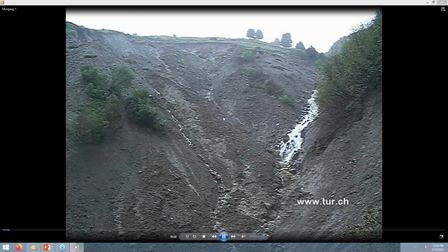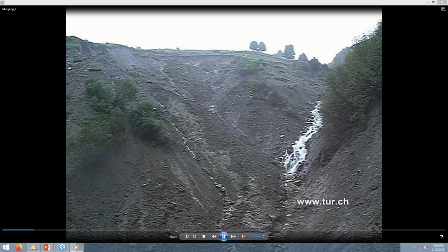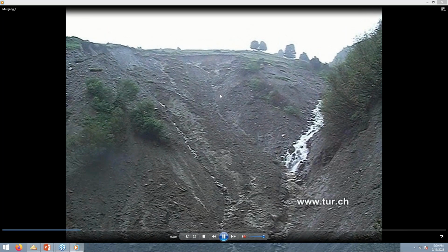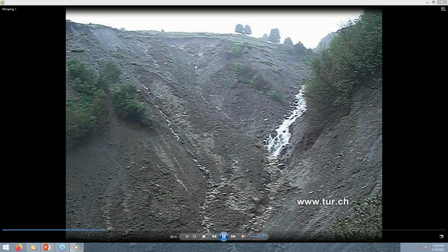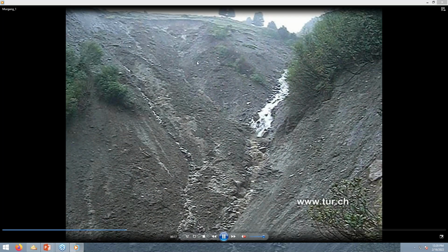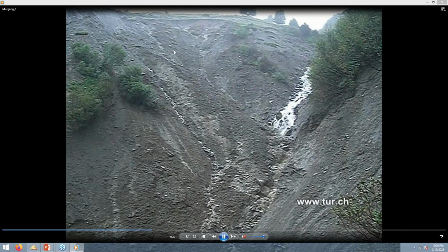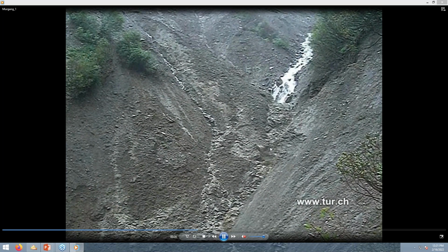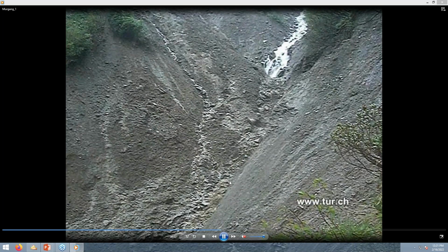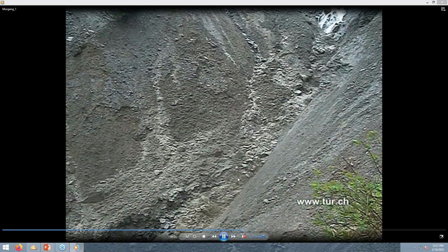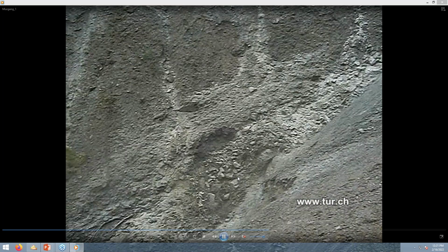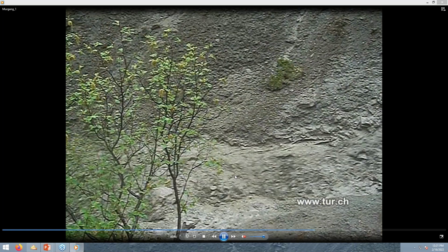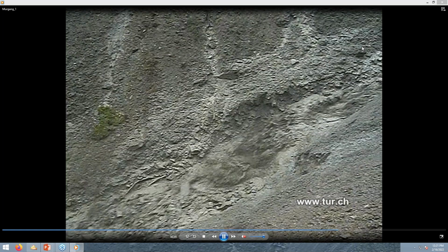Let's watch that again because it's fairly instructive. You can see that you're somewhere on the order of 20 or 30% concentration by volume based on the sediment loading from this. You can see some of the sediment coming off this fairly erosive structure here. This is more bank failure and hill slope sloughing coming down, but now it's moving into the channel. Okay, and there's some sediment here, but watch where it mobilizes all this sediment in this next reach. And you can see that it greatly increases the amount of sediment from the bottom of that channel. Okay, so let me stop this.